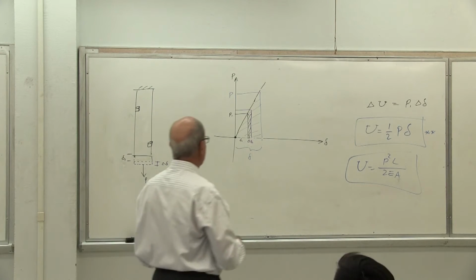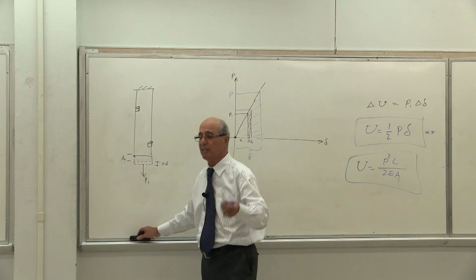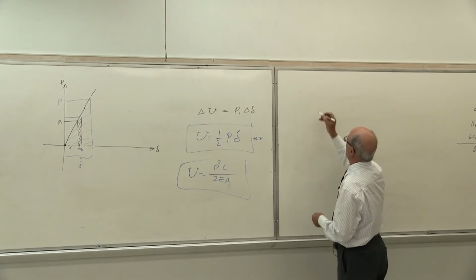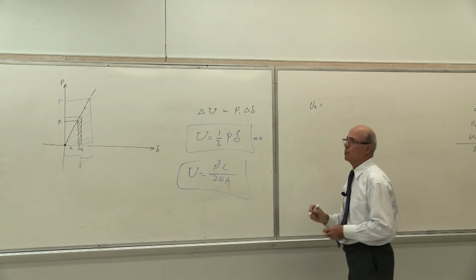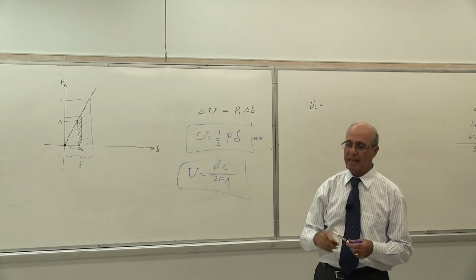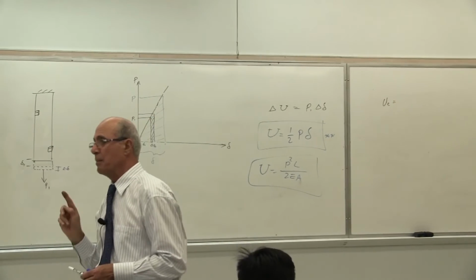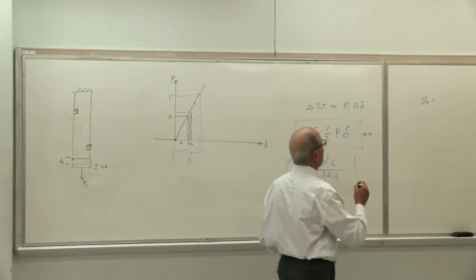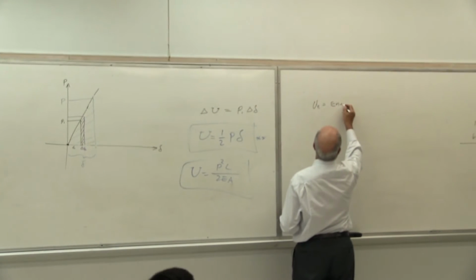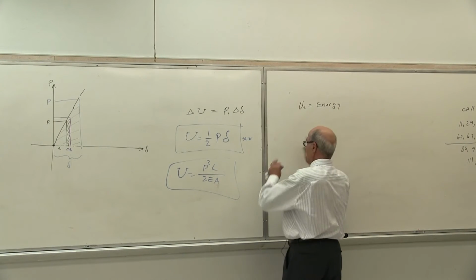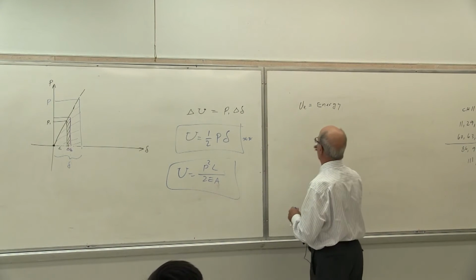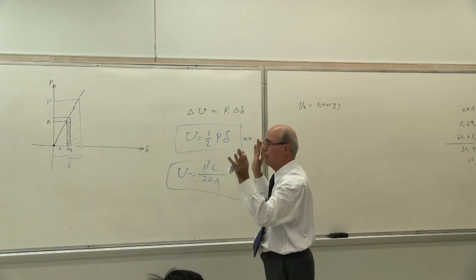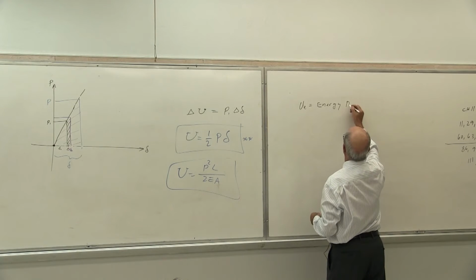So based on that, I'm going to define a strain energy density. Please write it down. The strain energy density, which we call small u, typically with an E subscript, is the amount of, first of all, it's energy density. Is this still for axial loading? It's for everything. That's the definition; it has nothing to do with one case or the other. I use it for that one, then I expand it, but this is for every problem. Doesn't make any difference.